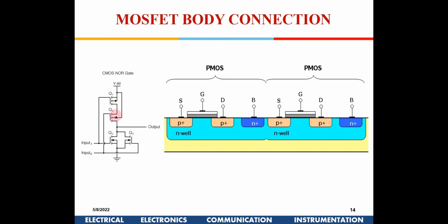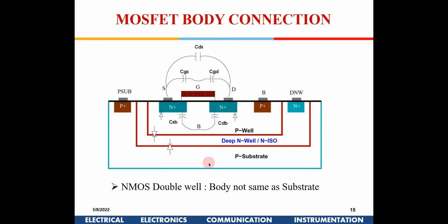You can't do it here, because again it would happen if you are connecting to VDD out here. There is a possibility that this source or this drain can be ground. If this is switched on and these are switched on, this will be 0 out here and this will also be 0 out here. So if you do a short here, there can be a connection from VDD to ground. So when you have different PMOS in the circuit, each of the bodies should be separately connected to the highest potential available in the circuit, which is generally VDD. So you have to take care of these things also.